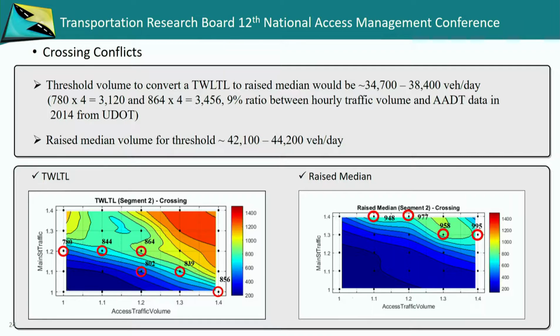Now, I've done other research in the past where our threshold came in a little bit lower than this, about 26,000. And again, that's where this was more subjective, of, okay, we've really bumped over into this cyan world, but really we should be changing that, I think, a little bit before we hit that 35,000 ADT value.